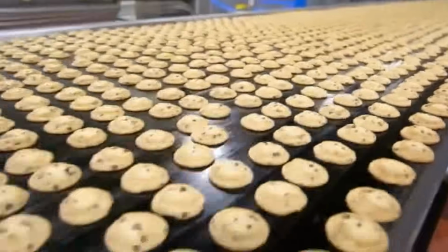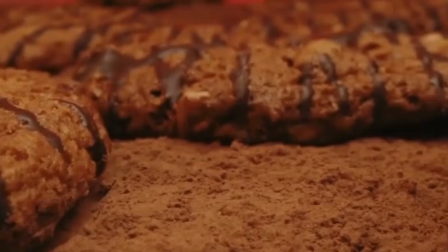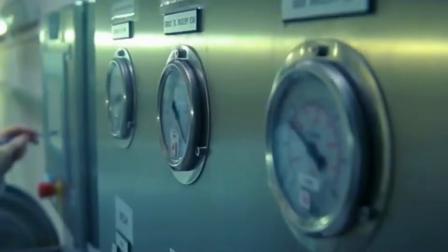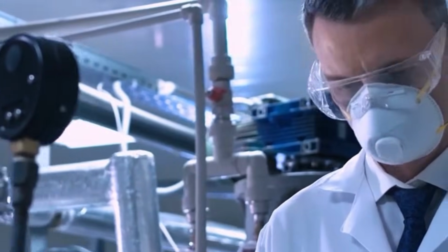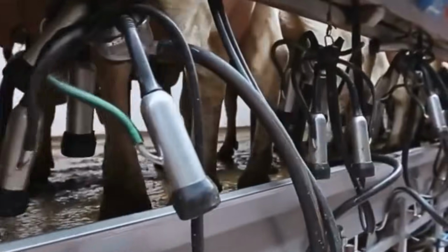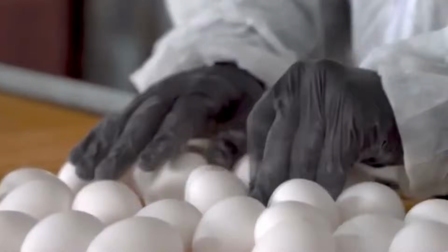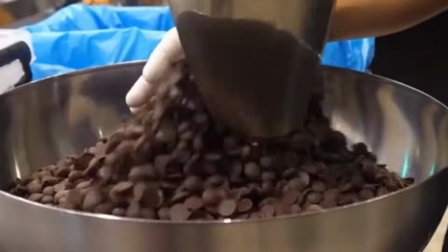A rotating arm or turntable applies plastic film under tension, with pre-stretch rollers ensuring optimal film usage and secure load containment. Wrapping cycles are adjusted for pallet height and weight. Each pallet receives a scannable barcode label printed by an industrial thermal printer. Labels are applied on two adjacent sides for redundancy. Pallet data is logged into the central warehouse system for tracking and inventory.